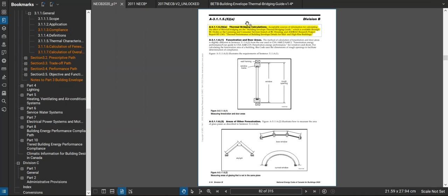And so what do we see right now around where I live in Calgary? Going back to the 2011 energy code, back in those days, the normal amount of insulation on the outside of a building would have been maybe 75 millimeters. The exception would have been 100 millimeters. Once the 2017 energy code came into effect, pretty much from what I'm seeing, the standard is 150 millimeters being put on buildings. So as we just saw, a picture of 150 millimeters with a clip and rail system probably isn't going to meet energy code in a prescriptive form.